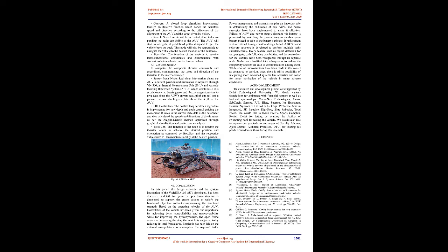Software stack structure. The software stack has been developed using Robot Operating System Kinetic, and computer vision software was developed using the OpenCV library. The stack was designed as independent, compartmentalized and parallel running nodes, each dealing with different functionalities, which work in tandem to achieve a common goal. Use of ROS for stack design helped in enforcing decentralization, process management, adaptability, easier debugging, and implemented communication between nodes through custom messages and topics.